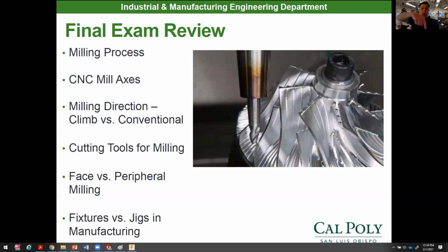We can start moving it around, that we calculated the feed rate for, but based off of the direction that we cut our part, moving around the outside of the part clockwise and the inside of the part counterclockwise, we would create a milling direction of climb milling.